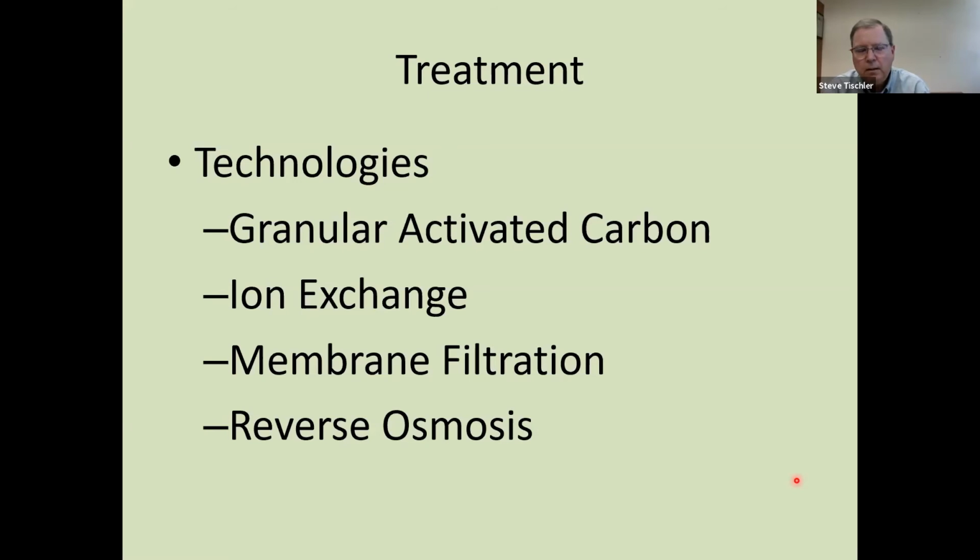And it turns out that the most common filtration technologies are very efficient at removing PFAS, to the degree that they're removed to below the detectable level. So these are the technologies that are primarily used: granular activated carbon, of course, ion exchange resins, membrane filtration, and also reverse osmosis. All four of these technologies, which we're very familiar with, are very effective in removing PFAS from